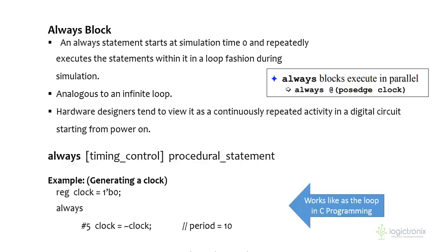Another important thing is the always block. The always block runs in parallel, and it is utilized for executing sequential statements like if else and case statements. So an always block is needed for conditional statement based programs. It also consists of the sensitivity list.